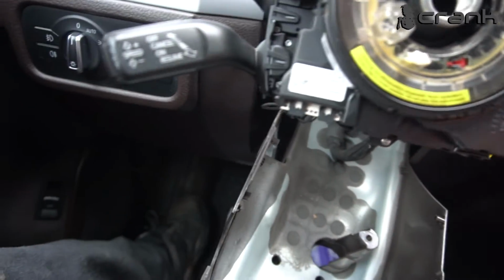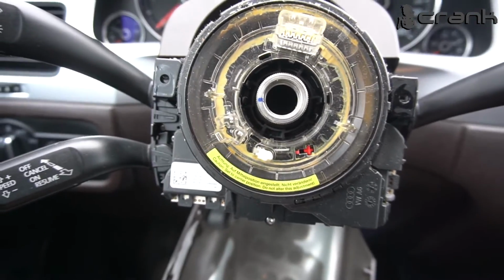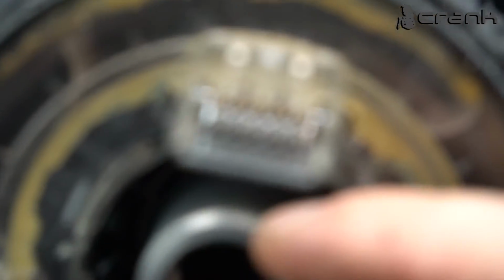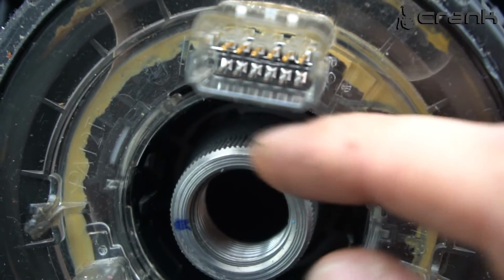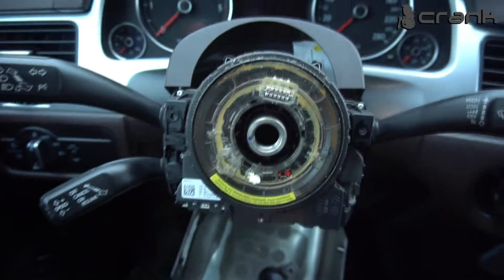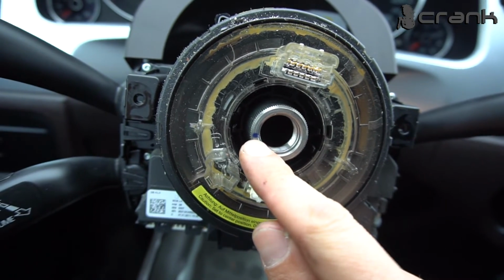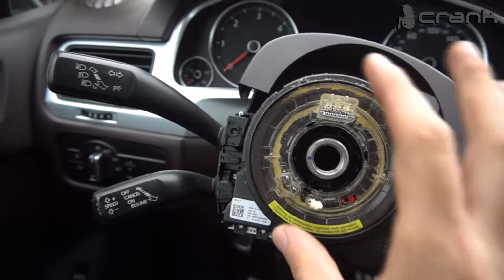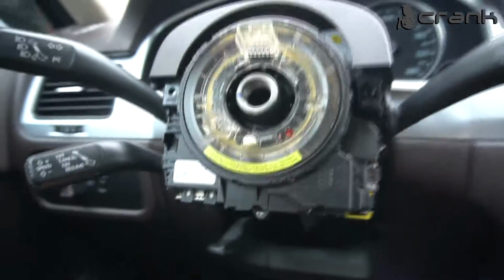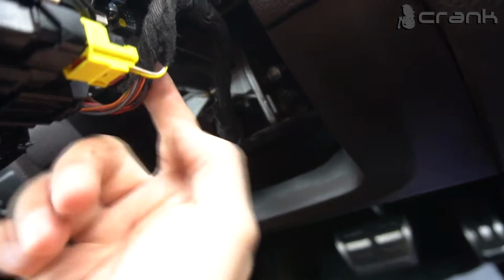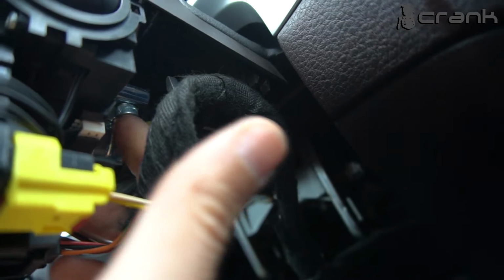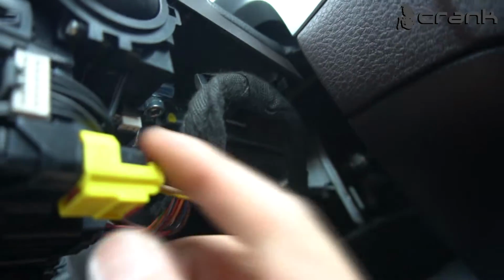We already have access to the thing which we're going to work with, and actually we don't have missing teeth here. As you can see, we don't have missing teeth, so you can mess up the reinstallation of the steering wheel, so it's a good idea to put some marking when you're removing the steering wheel. Now, to be able to remove this whole assembly, the steering wheel column module, let's say, we're going to need to undo this bolt behind here. This Allen key, probably 5mm or 6mm.